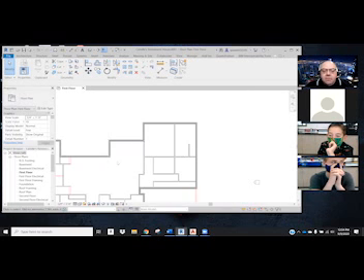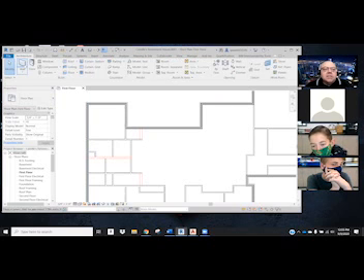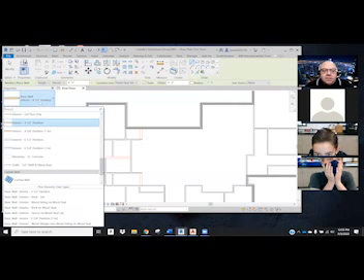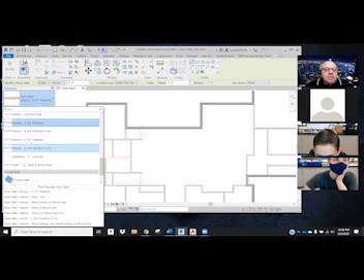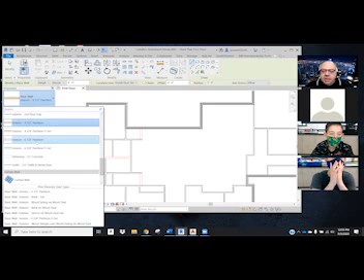And I'm going to start my work over here by putting in my 2x6 partition wall for my plumbing. Remember, I had to have a 2x6 behind my water closets. So, architecture wall, I'm going to switch it from the basic partition to a 6.5 inch partition. Again, commercial, you can use the 1 hour, and residential uses the not 1 hour, okay? So it's a 6.5 inch wall because it's 5.5 with a 1/2 inch on each side. That's where the 6.5 comes from.